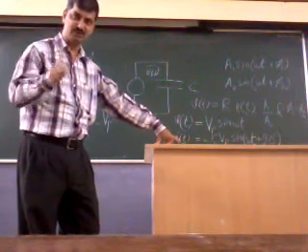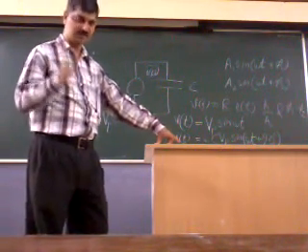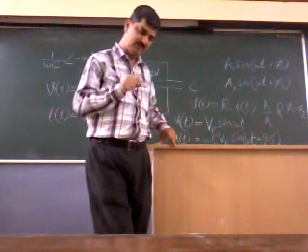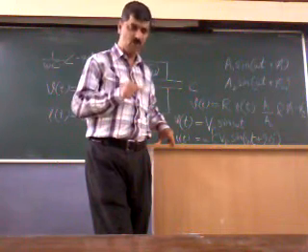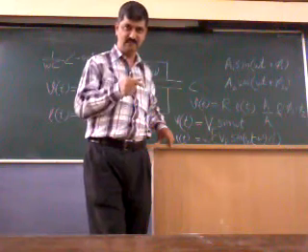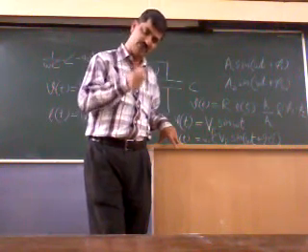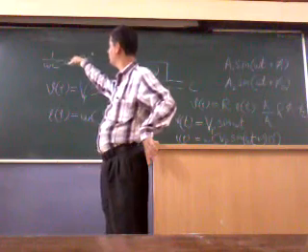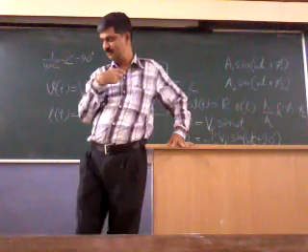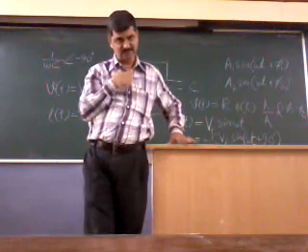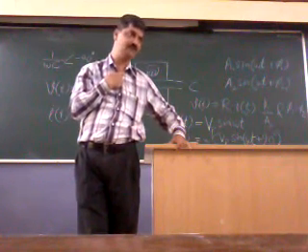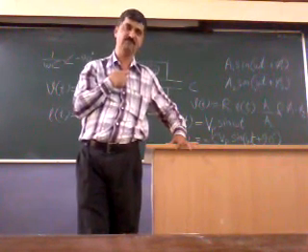It is not an instantaneous ratio. It is the ratio which explains the overall relationship between voltage and current, that is, their amplitudes. By looking at 1 upon omega C angle minus 90, what do I get? I get an idea that for voltage upon current, the amplitude ratio is 1 upon omega C and the phase difference is minus 90.